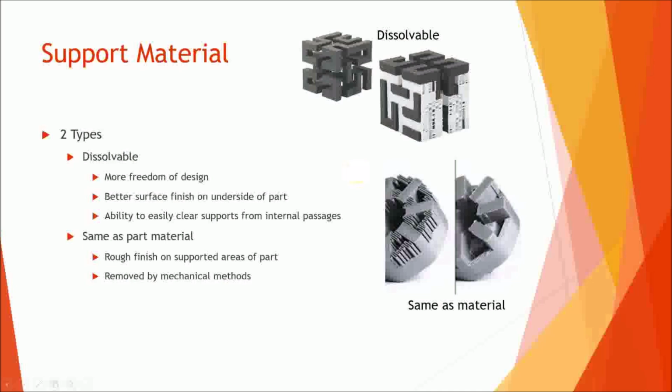If you are working with dissolvable supports, you have a lot of design freedom. It reduces post-processing costs. And if you're dealing with supports that are the same as the printed material, you'll probably want to minimize the amount of supports that you'll need as much as possible, and we'll talk about that in the next few slides.